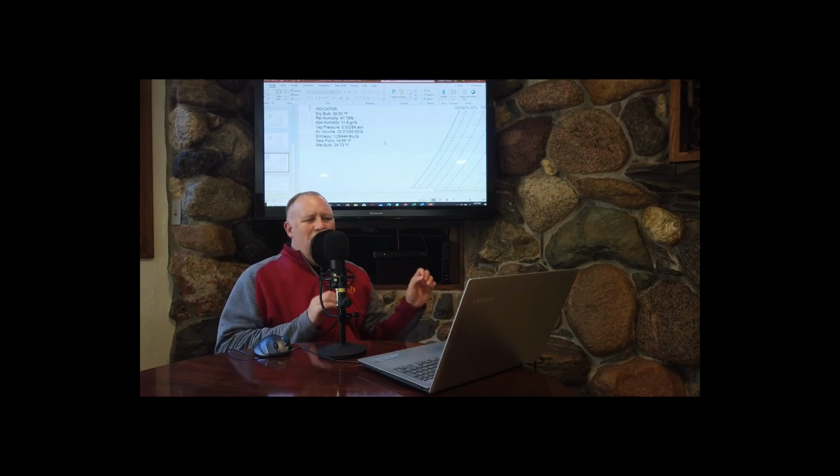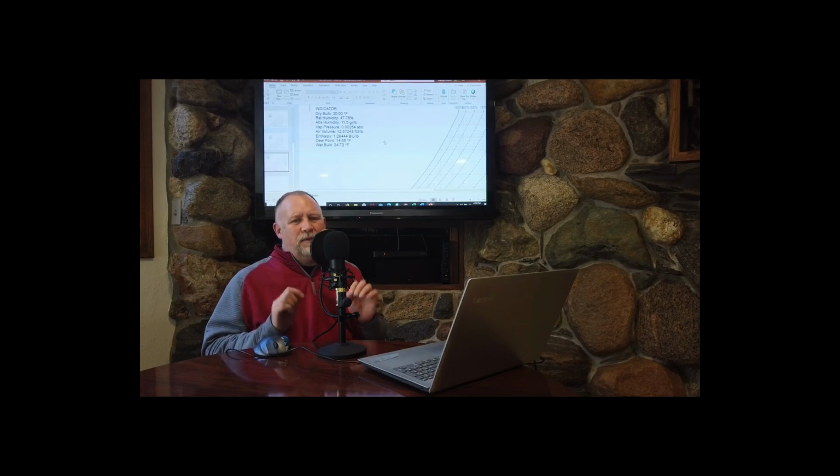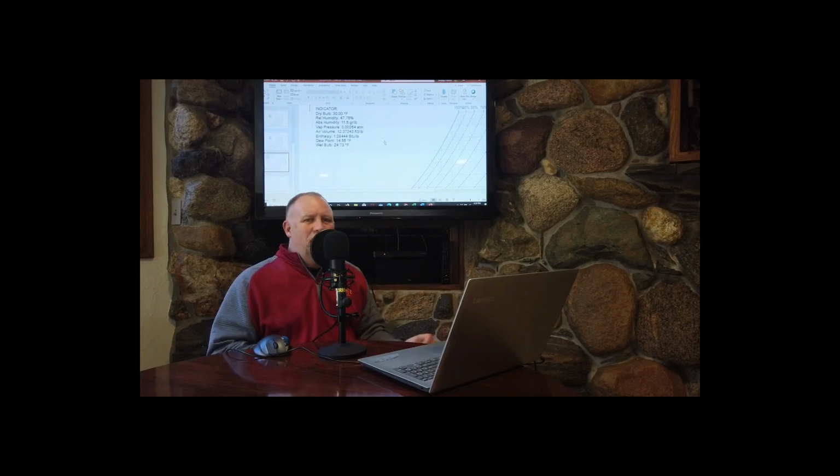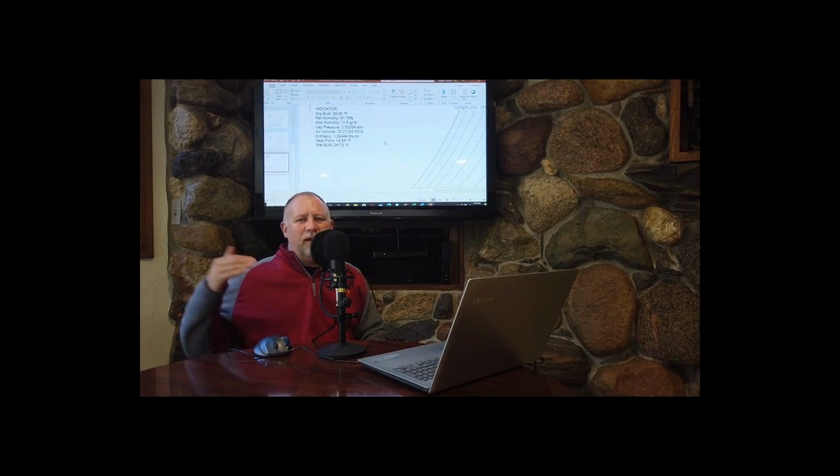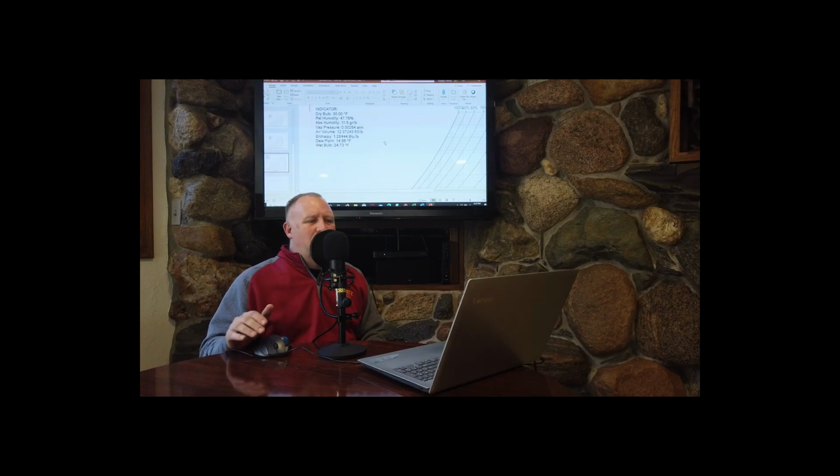Relative humidity is meaningless without knowing the dry bulb temperature. 50% relative humidity can be dry, 50% relative humidity can be tropical. It all depends at what dry bulb temperature you are getting that relative humidity reading.